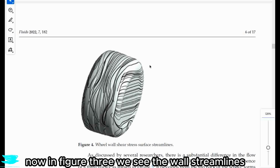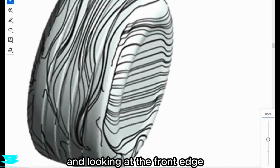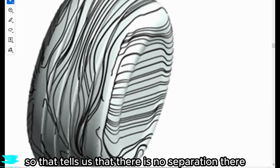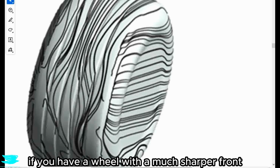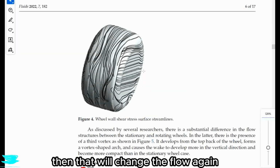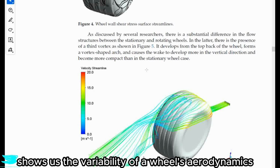Now in figure 3, we see the wall streamlines, and this is for the stationary wheel again. Looking at the front edge, so this front part here, the streamlines are straight. So that tells us that there is no separation there. So this edge is round enough to keep the flow attached. And again, if you have a wheel with a much sharper front edge there, the sharper shoulder, then that will change the flow again because it may separate. So that again shows us the variability of a wheel's aerodynamics.